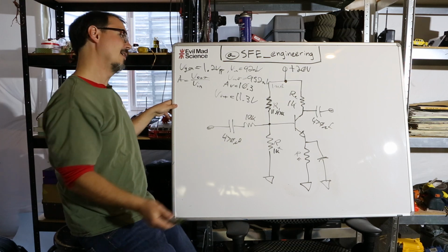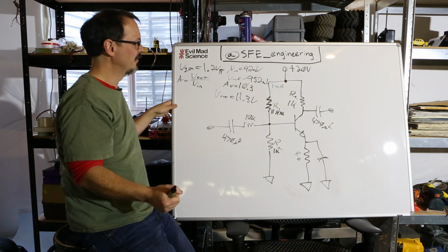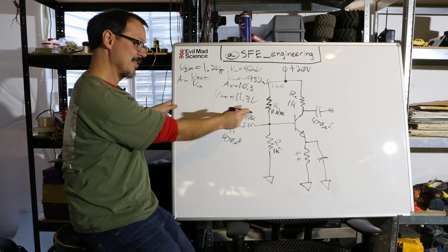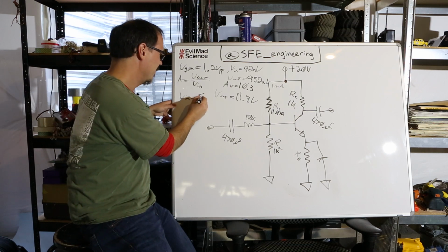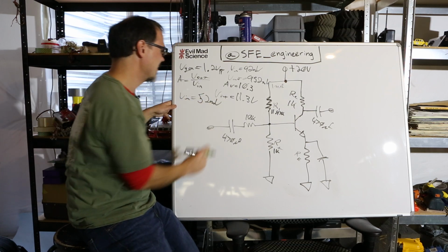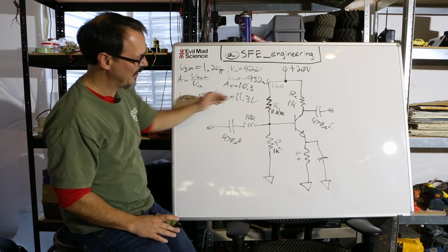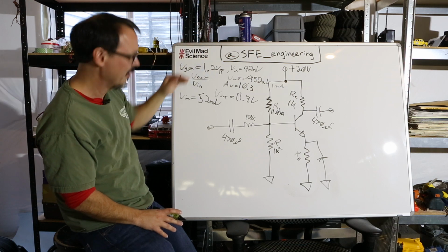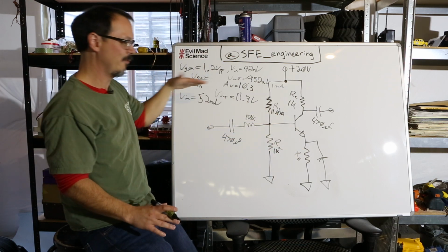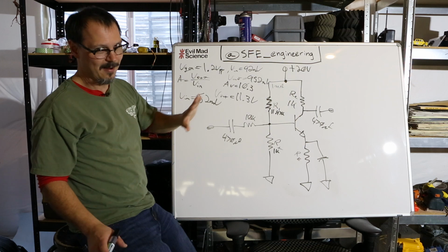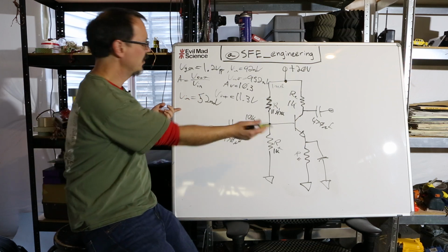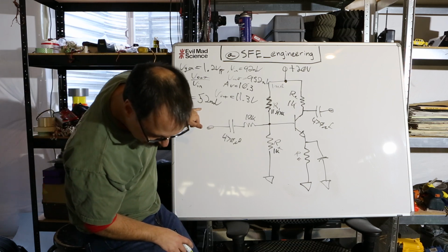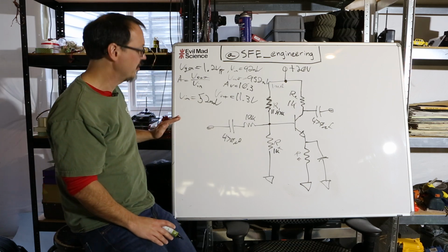And you might go like, oh, okay, so 11.3 divided by 92 millivolts is, no. Go back and measure your V in, because I'll tell you something, that guy changed. V in is now 52 millivolts, okay? So where the input impedance was once, and if you calculate this out, it actually comes out to be 830 ohms. Without that cap, remember we calculated 843, turns out it's 830 in real practice. But when you put that cap in, suddenly you've got 52 millivolts, and that brings us down to 452 ohms